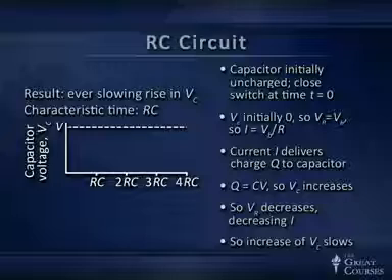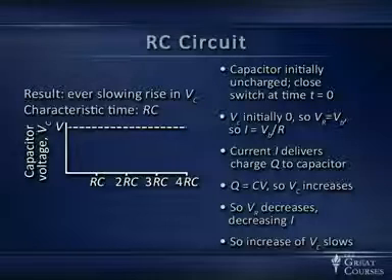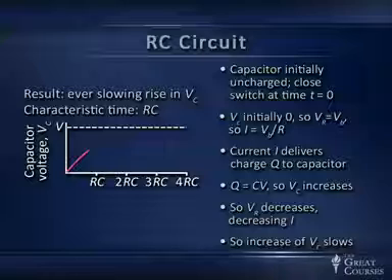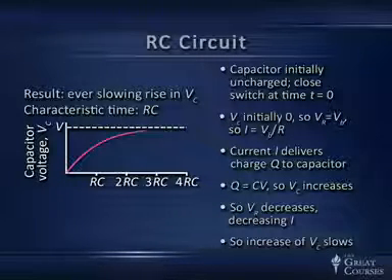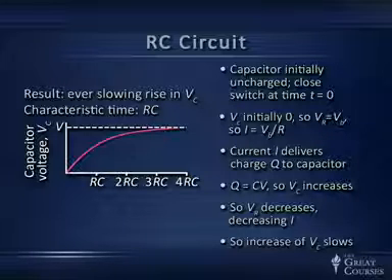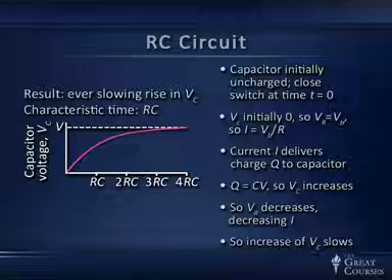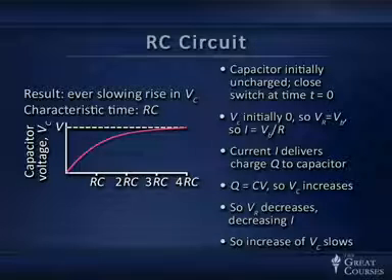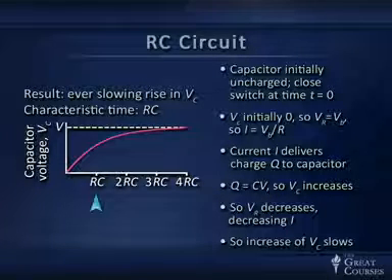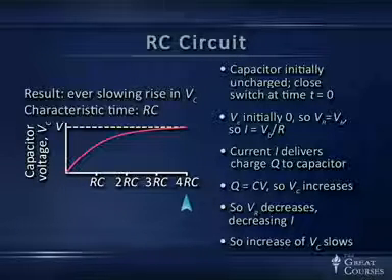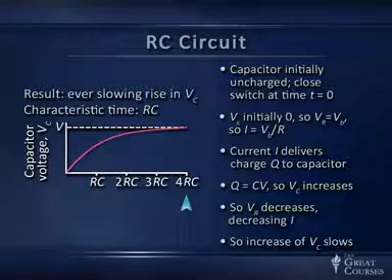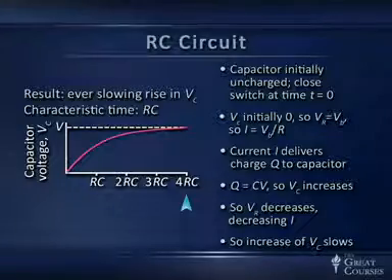And here's what we expect the voltage across the capacitor to look like as a function of time. It starts charging rapidly, but it slows down and slows down as the rate of current flowing through the resistor decreases and the rate of voltage buildup across the capacitor therefore slows. A capacitor gets to about 2/3 of its final charge in about one of these time constants RC. I've shown you out here to 4 time constants RC, and by then it's almost fully charged to the battery voltage. Well, let's take a look at how this works in the real world.